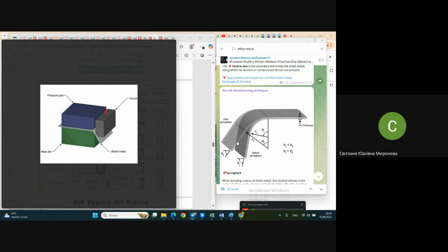If you know from previous experience, statistical data and scientific articles that for this thickness and this radius it springs back 5 degrees, what is the obvious decision to improve your tooling so that you have 90 degrees after bending, understanding that it will compulsorily move back 5 degrees?